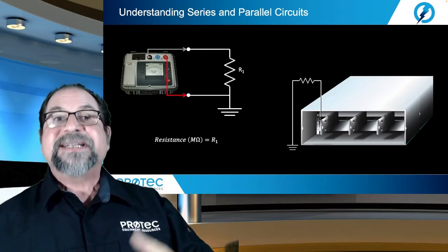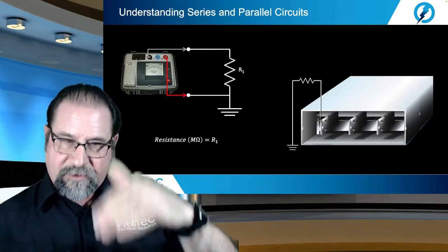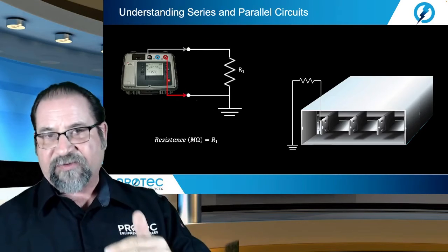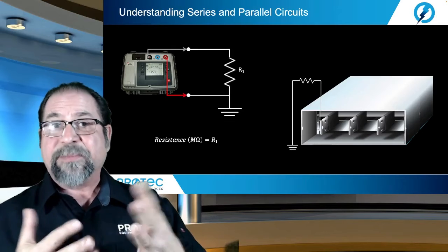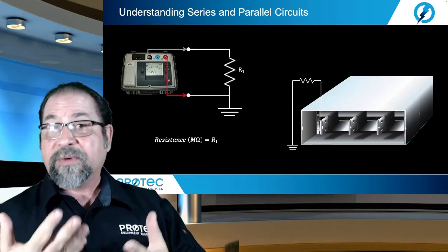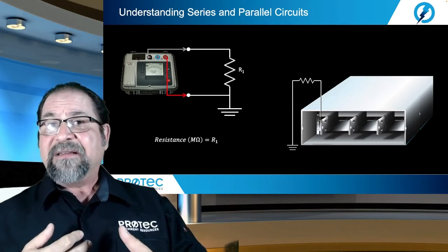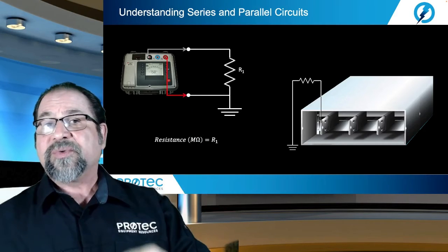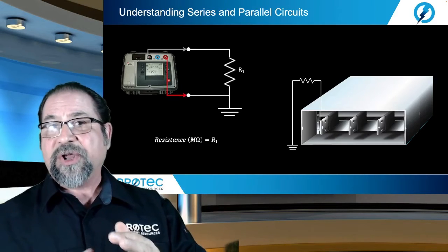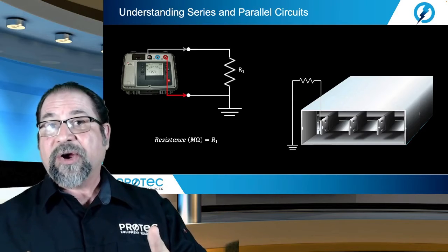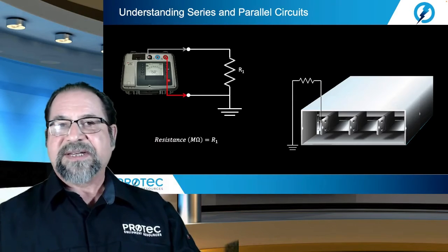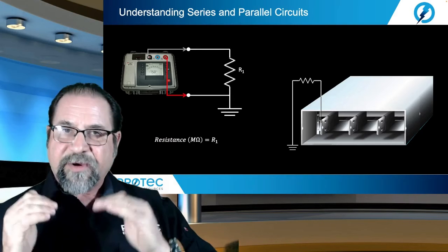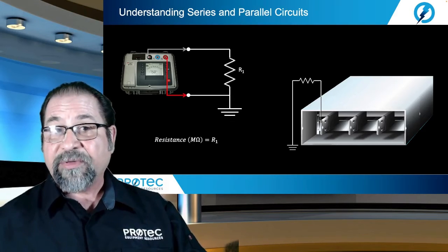We measure several currents: capacitive charging current, which starts high and drops relatively quickly, and absorption current as the insulating material goes through polarization. And effectively, when this all occurs, we then measure what's known as the leakage current, the current of most interest, the current that's traveling through the insulation, which should be a very, very low current if everything is good and healthy.